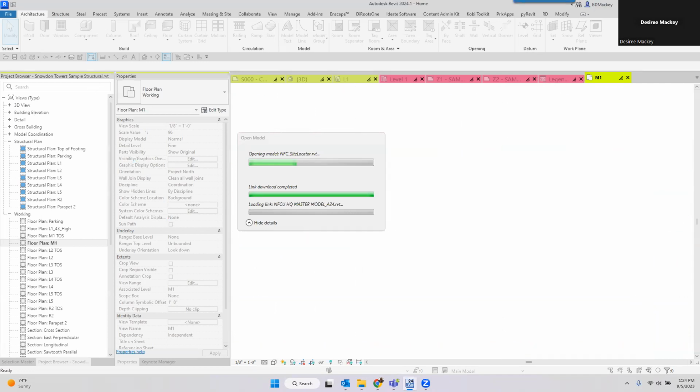So that's how I go through and do it. It sounds really complicated, but it's the easiest way I've found, because now I've got that coordinate and I've got that separate file. I didn't realize this was going to take forever. I literally just had this one open on Friday. But I have that set up and located, so now I can just move those buildings, reposition them, then go back into the files, remove the site locator, and reacquire those coordinates.